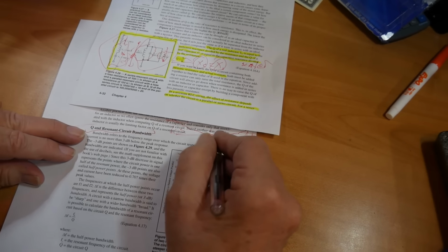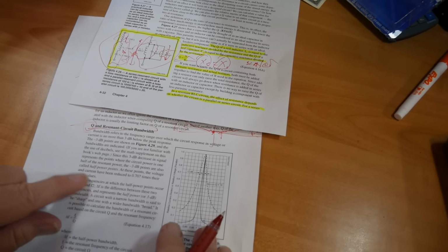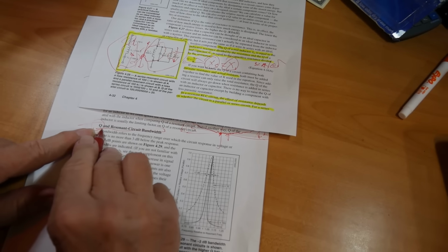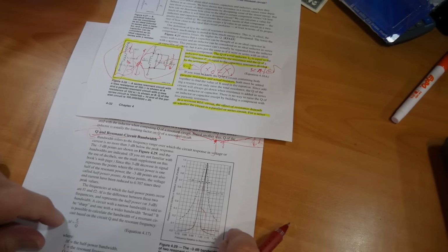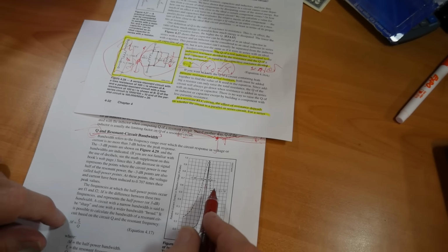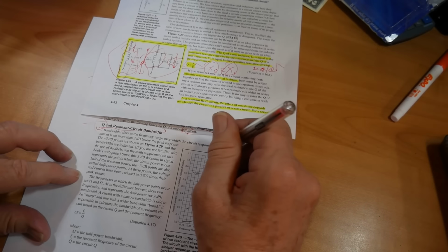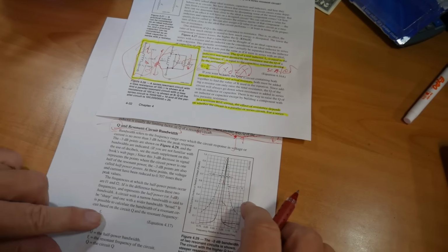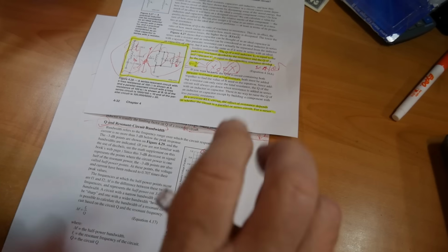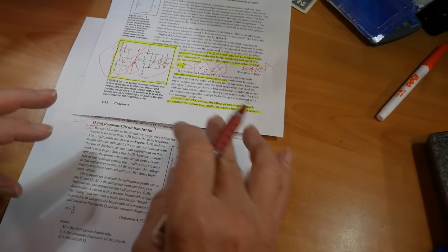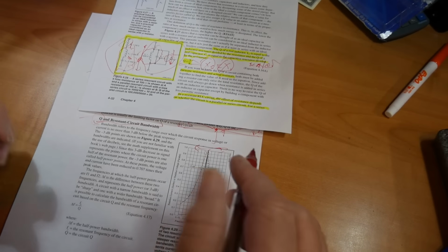If you increase Q, which is the case when you are using a mag loop, antennas have very high Q, which means very narrow bandwidth. Okay? So a high Q circuit only resonates within a very small range of frequencies. A low Q circuit can be satisfactorily resonant. It's really technically resonant only on one frequency, but you move far away from it and it still works fine. Okay? So there you have it.